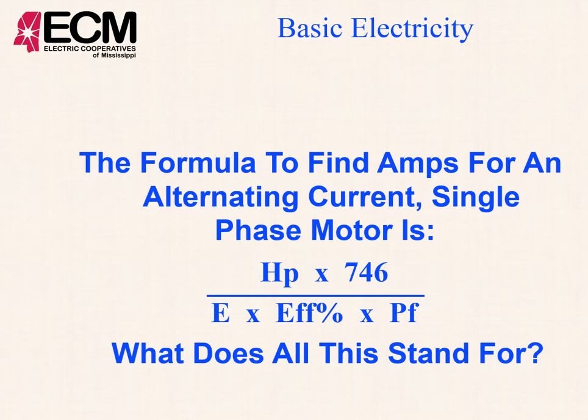You have a huge current influx, current inrush, but yet our voltage gets dragged down because we've increased the resistance there. Okay, so that has to be accounted for. It happens definitely at the beginning and the start of the motor. That's one of the things that capacitors correct. They're hooked on there. When there's a deficiency, they discharge and keep that voltage up and try to keep that voltage and current running together.